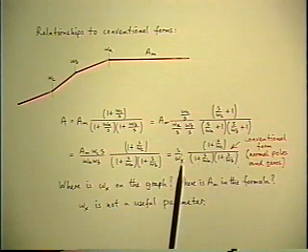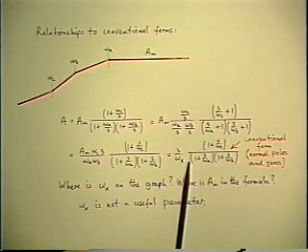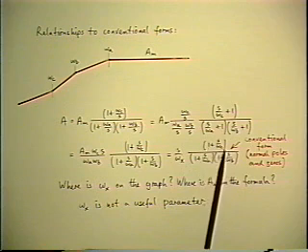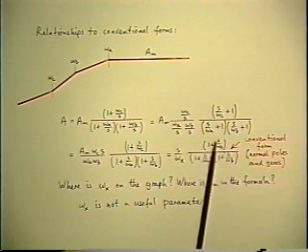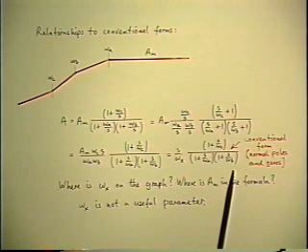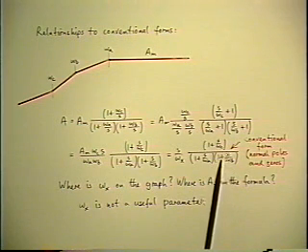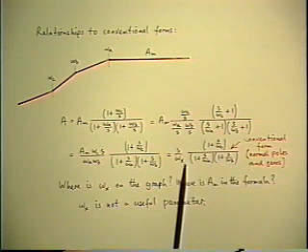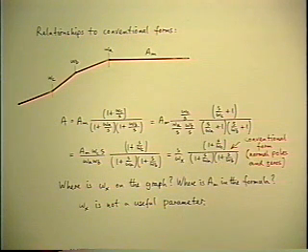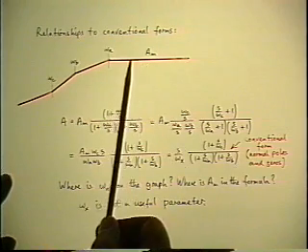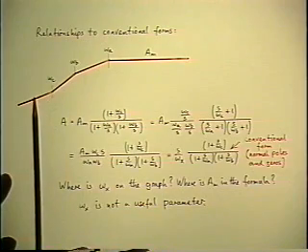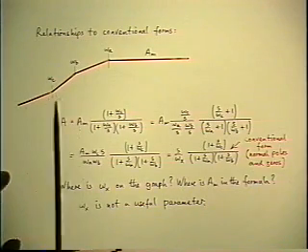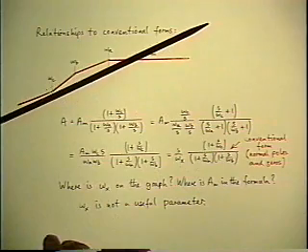So you can expose only the first term. The rest of it would go to 1 if you made the frequency lower than any of these three corners. So S over omega x must be the zero frequency asymptote. So what that would mean on the picture is you'd let S be so low that it would be even lower than the omega C, and all that's left is this asymptote.